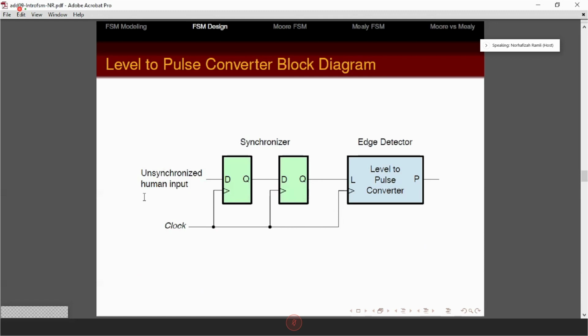So your first choice, you have an asynchronous input from human, from your hand, so you can delay the signal using a synchronizer. You use two D flip-flops. This basically delays so that if you have 2 or 3 very fast inputs, only the first one is captured and transferred here.